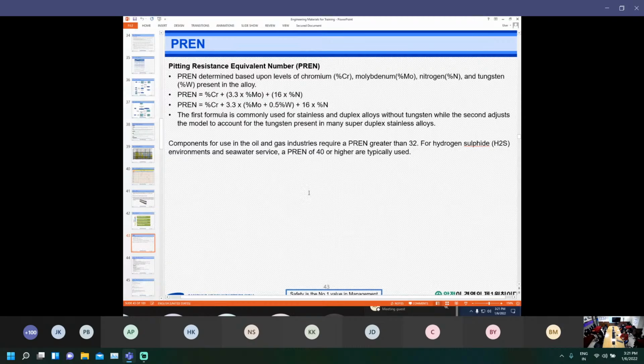In our industry, we generally recommend using it if the PREN number is more than 32. And if you are dealing with H2S service, SO2 service, or seawater service, we recommend using a PREN number more than 40.